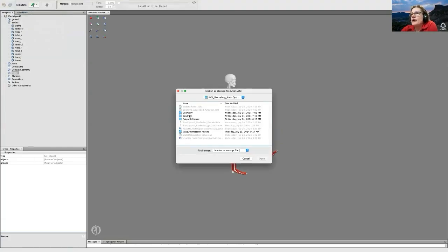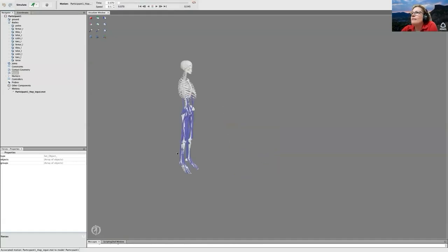And we're going to go within this folder. There's a subfolder called Input Files. It has 2 files in it, one labeled kinematics and one labeled ground reaction forces. Make sure that you select kinematics.mot. Go ahead and open that. And if you go here to the top of OpenSim, click this looping button to the right of the time bar and press play. You can see I've put my speed at 0.5, so you might consider moving your speed down a bit so you can visualize it.